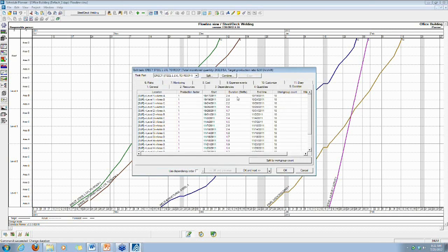And that's represented in our Durations tab here as an individual duration by location with an assumed work group count of 10. Now, it's not often in a Gantt chart schedule or a CPM schedule that you see durations that are widely varying or have decimal points in them. So if you wanted to go through the process at this point of exactly aligning the location duration with the duration that's specified in your CPM schedule, you could do that here in this Durations tab